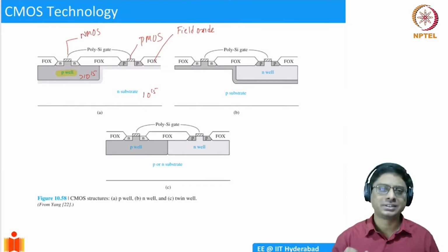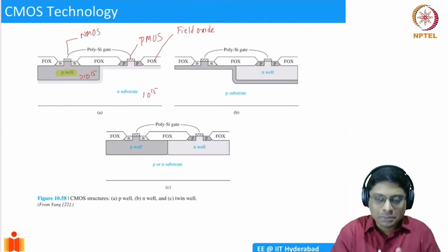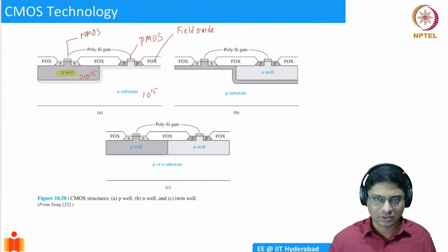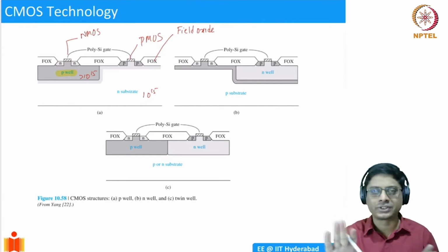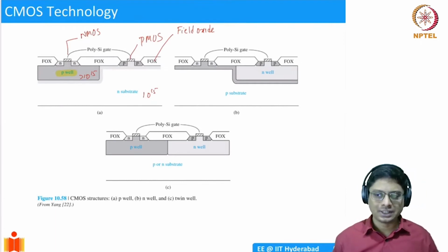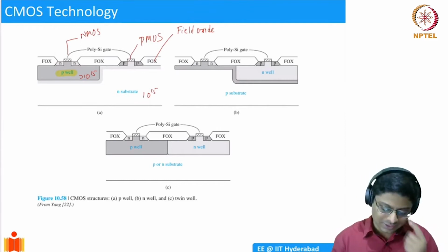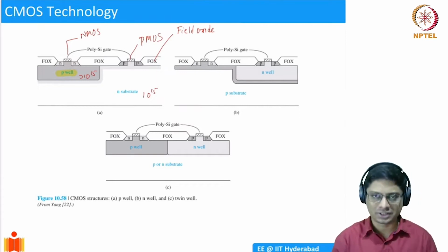It's a thick oxide. We saw gate oxide, which is a very high quality thin oxide, but you can also have a thick oxide, which we call field oxide. That is essentially isolating, creating barriers between different MOSFET devices. By the way, this is only one axis. We are showing a cross section, but in principle, this field oxide will be surrounding the MOSFET in all directions. It's like a ring you're forming around a MOSFET to isolate it from other MOSFETs. So that field oxide will be created, and you can then connect these devices to form various configurations.